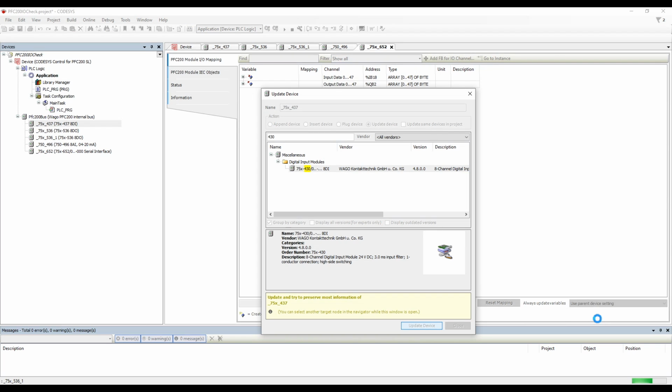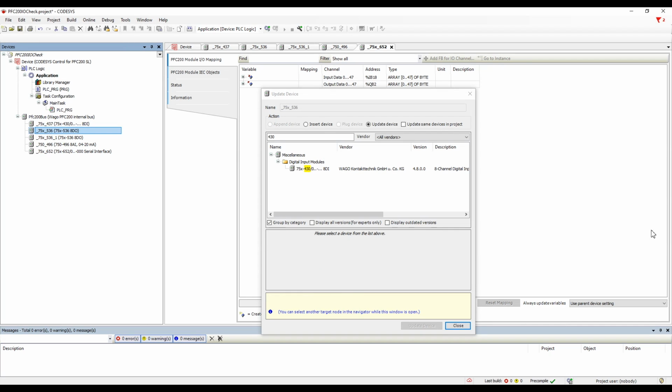That is why I started with the scan. So how exactly we can scan, and then we can also add or update the devices directly into the IO configuration. Sometimes it gets all the IO configured in the IO card as a generic module, but we need to update as per the configuration. So we will do it for all the different IO cards, and then we will go for the download.